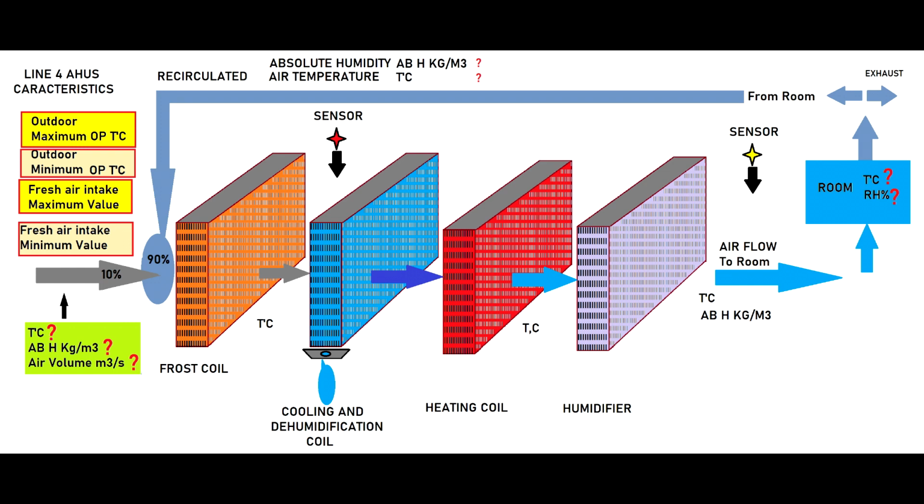Here you can see the heat exchangers, and you know, guys, if you push more air than the heat exchanger can support, and if you reach the saturation point, the heat exchanger won't be able to remove moisture from the air or will not heat the air enough. So every time we do this type of calibration, we have to make sure that we do not calibrate only these differential pressure modules or differential control modules, but I prefer loop calibration, and also I prefer cross references with other